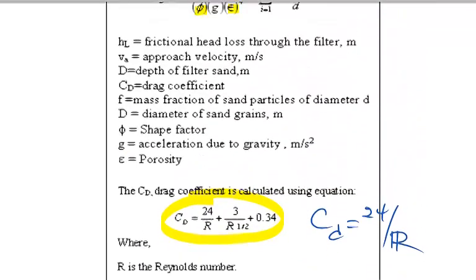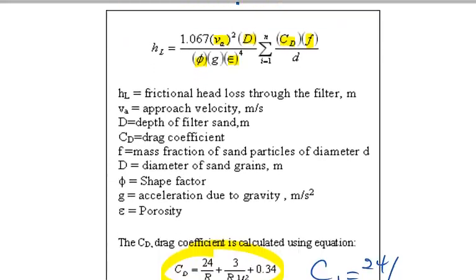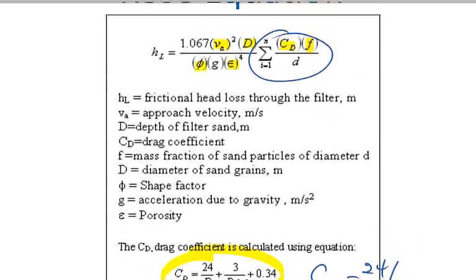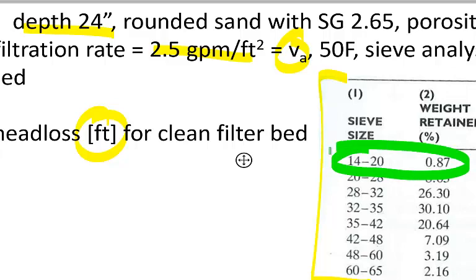We have these particular values that have been determined or provided. What we're trying to do is set up a spreadsheet or a table that could calculate these. We're going to be looking at the sum of these variables in this calculation. Let's start with our first set of data, what I've got here in green: our sieve size and our percent retained.